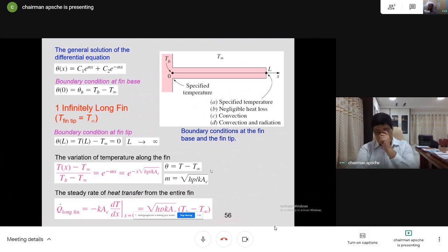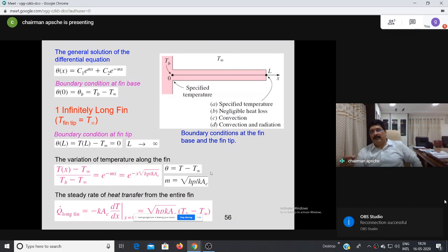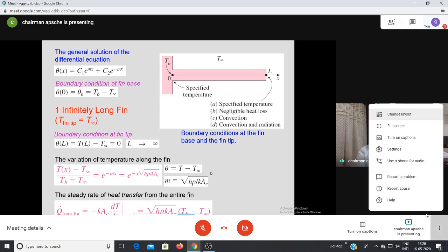So the Carnot cycle is not a practical cycle because imagine half of a revolution it runs fast, half of a revolution it runs slow. It is not going to be possible. But still, we use the Carnot cycle as the reference. Similarly here, the maximum heat transfer is the heat transfer taking place at the area of the base. Heat transfer with fin is any of these equations depending on the fin condition. So you can calculate.